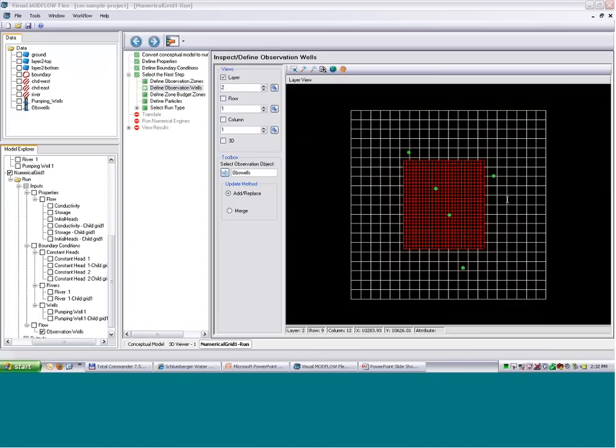There's a quick question before I proceed. How does it deal with the river at the intersection of a parent and child grid, say the coarse grid at the parent level and the finer level? Hopefully the illustration I just showed answers that. So you can have river cells that exist in the parent grid from the same reach, and river cells that exist in the child grid. And then during the two-way coupling, Modflow LGR automatically calculates the appropriate heads and fluxes between those two numerical models.